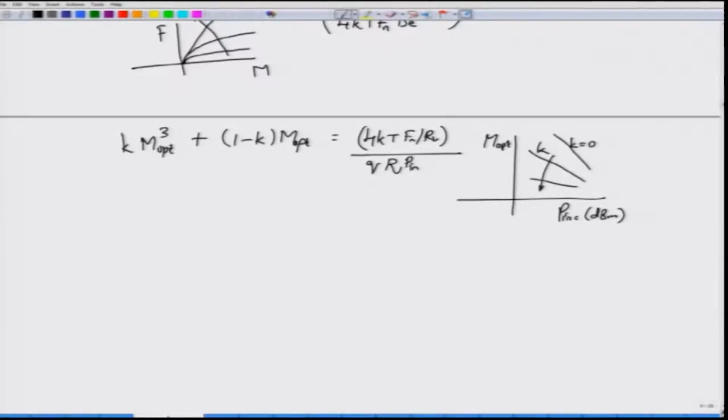There is one additional term by which we quantify the photodiodes, and this quantity is called the noise equivalent power. Noise equivalent power is the situation where, as you start reducing the optical input power, the signal to noise ratio becomes exactly equal to 1, at which point signal power is equal to noise power.